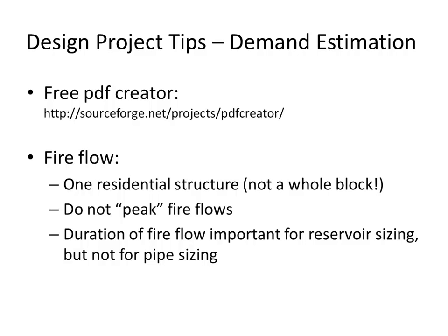Remember that for the fire flow, it's not the entire block that's on fire, it's just a single structure, and fire flows don't need to be peaked in the same way that your ordinary residential demands do. And so you'll be peaking the residential demands, but then adding the fire flow on top of the average daily, not on top of the hourly flow.